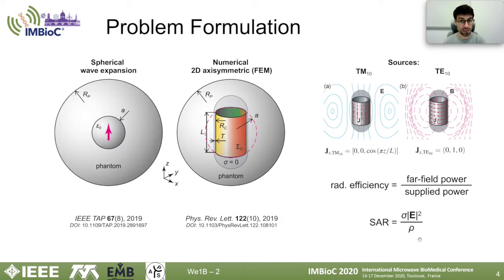So we start with the theoretical studies, and I would like to talk first about the fundamental limits for implanted antennas. Compared to the radiation into free space that classical antenna theory assumes, we deal here with a finite and lossy medium. And this implies two things. First, the antenna near field fringes into tissues, and therefore the parameters are strongly coupled with the electromagnetic properties of the neighboring tissue. And two, the resulting radiated wave is shaped by the attenuation, complex scattering and reflection, as well as re-radiation at the interface between tissue and free space.